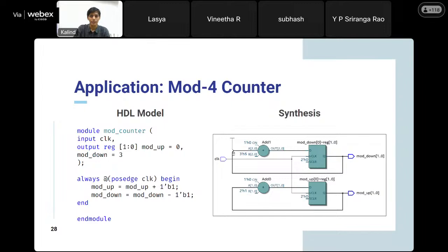Let's say your design is taking only 3K logic elements. You can go with an FPGA board having 5K or 10K logic elements, because your design can easily fit onto that. It's not worth investing money in a board of 22K elements, because that will be costlier. That's how you can select which FPGA board to use for implementing your logic design.